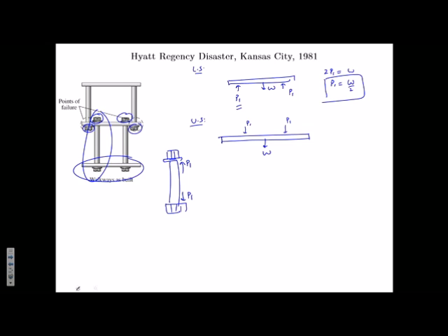Okay. And then you have these nuts, the outer nuts, which are also supporting the upper skyway. So that means these nuts will be applying an upward direction force on the upper skyway. Let's say that is P2. And I'm using the same symbol as I used in the previous slide, but remember, they are not the same numbers, right? I could have put prime everywhere, but it will just make it messy. So I'm just using the same symbol, but remember, the numbers could be different. So these are all the forces on the upper skyway.